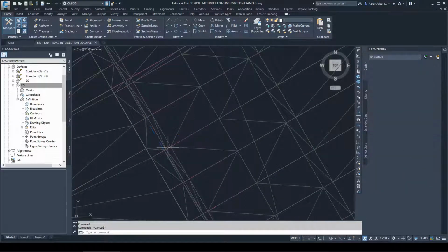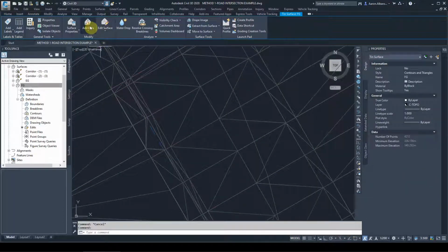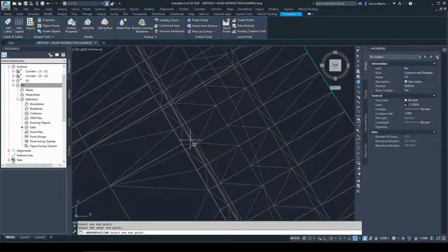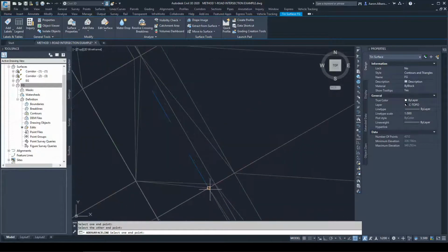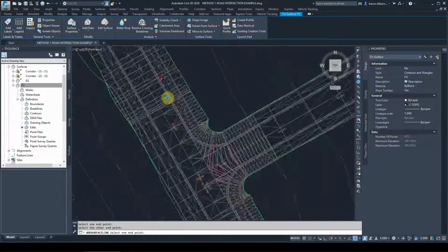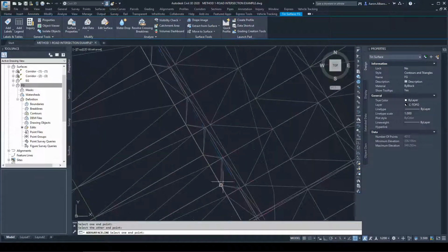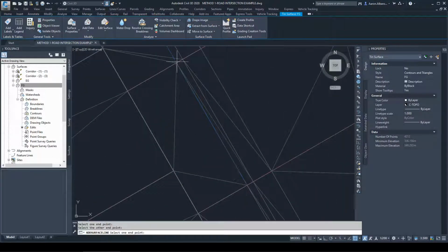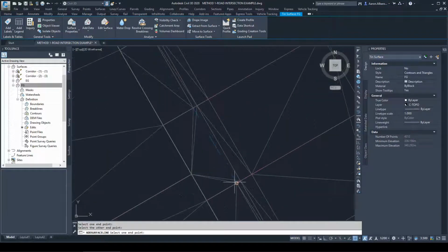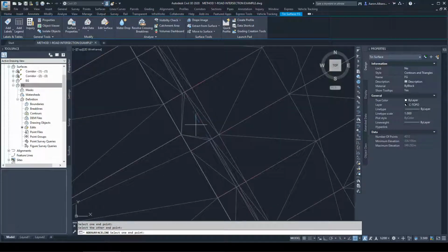So for this surface here, what I can do, edit surface, add a line, and I need that line to go from this point to that point there, and that will fix the problem. I've got another one here from this point to that point. Not sure if there's anything else on this side. There's two of them, and let's check this side. We've got plenty on this side, so I'll just fix them all. Got this one here, that one, that one, the last two.